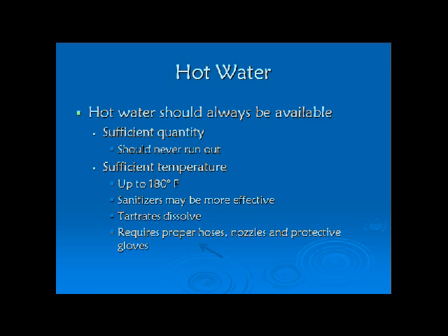And finally, if you do have hot water that's very hot, so you're pushing that 180 degree Fahrenheit mark, make sure that your hoses will handle that temperature at the pressure you've got. A lot of times standard garden hoses will not, and what you'll see is basically they start to bulge right where the fittings are, that bulge gets bigger, and pretty soon it thins out the hose enough that it will burst and spray you with hot water, which could cause actually severe burns at the temperatures we're talking about. So make sure your hoses will stand the temperature and pressure.